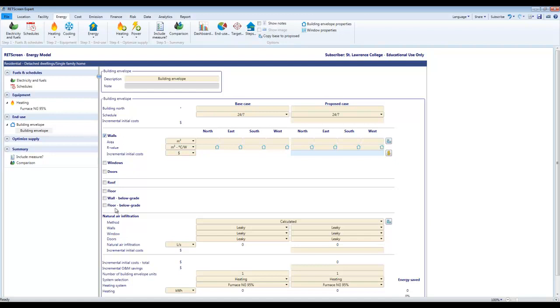These, by the way, are above grade walls. Below grade walls appear down here. So if I have more than one type of above grade wall, I'm going to need to put them on different building envelope zones because I've only got one R value here that I can associate with this wall type. If I've got wall types with different R values, I'm going to have to spread them around. That is if they're all above grade. If I've got below grade ones down here, that's fine.